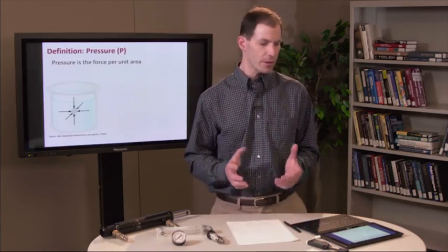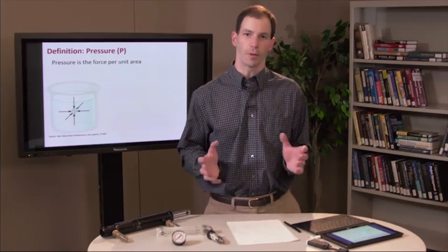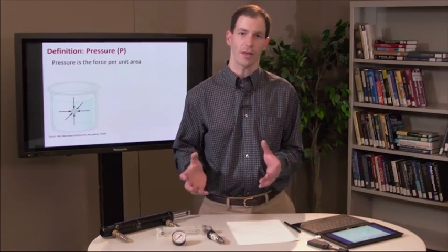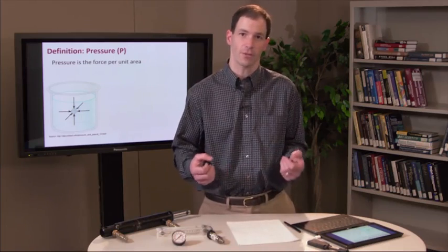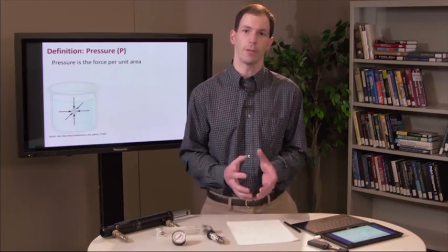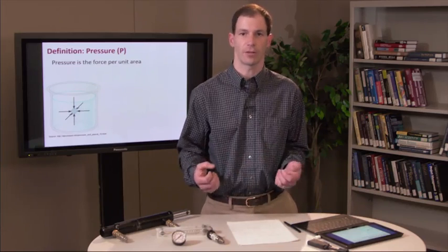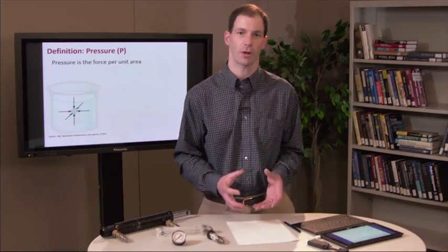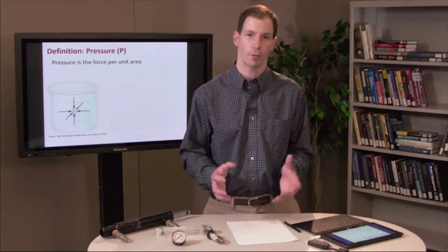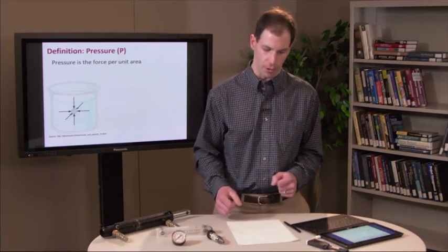Pressure is simply the force per unit area. And one thing I want to stress here is that unlike a solid, where you can have tensile force or tensile stress, a fluid can only be in compression. It cannot handle a tensile stress. And so these pressures we're talking about are always a compressive pressure in the fluid itself.